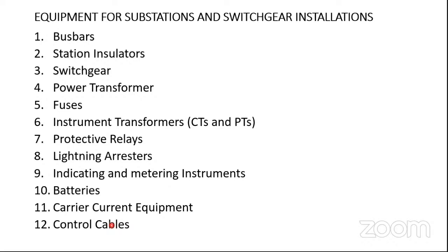The cables employed for this purpose are multi-core cables having 10 or 37 or 61 conductors according to the requirement. For laying these cables, generally ducts are run from the control room basement to a centrally located junction box, from where the conduits are run to the required points.